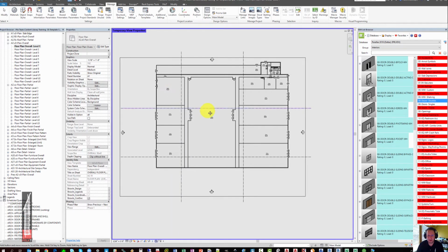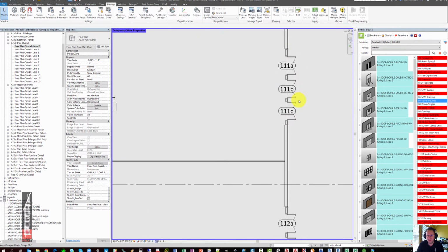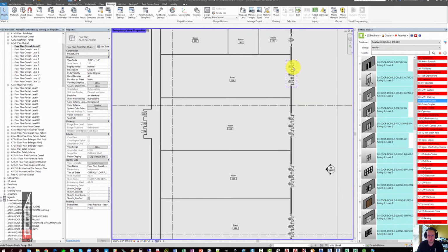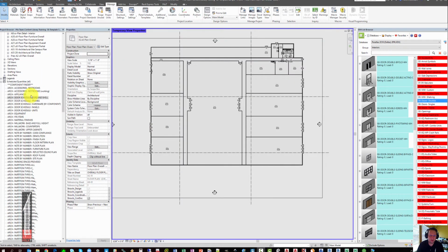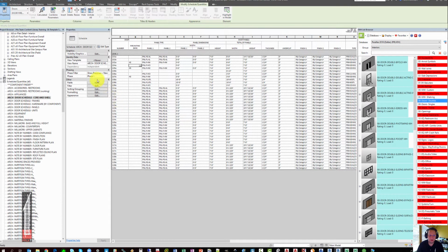the project. So here you'll see that we have a number of doors already placed in the project, and they are all numbered based on room number and then a lowercase letter. If we open the door schedule, you'll see an itemized list of all the doors that are in use in phase 1 of the model. There are a number of different door fields available in the door schedule, which may have been customized in your firm's variant of the Parallax template.